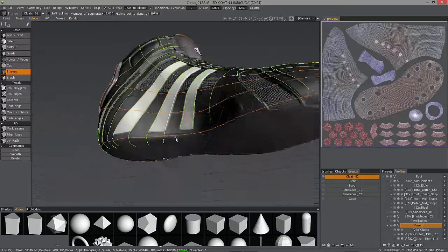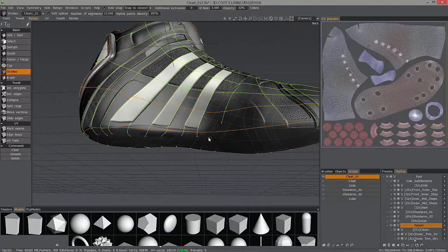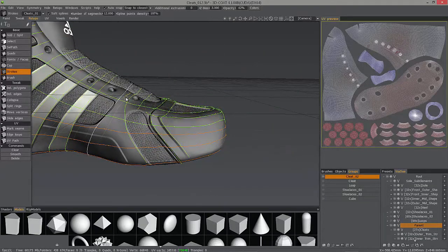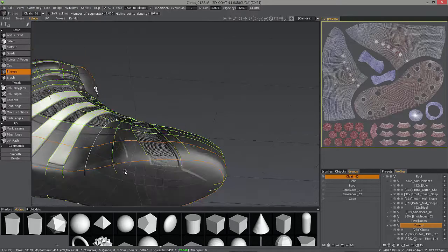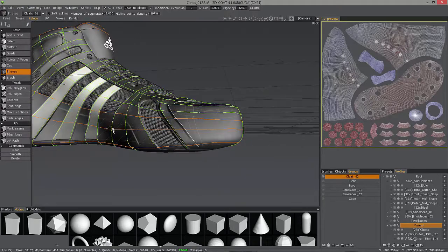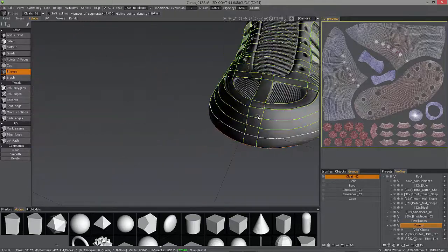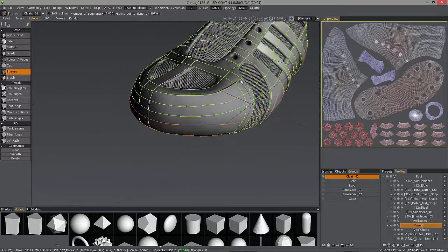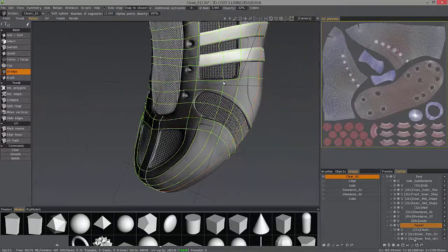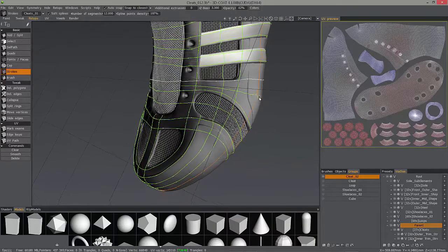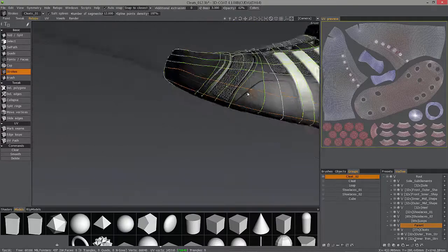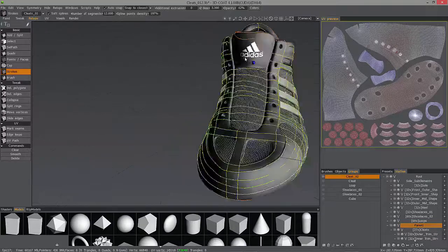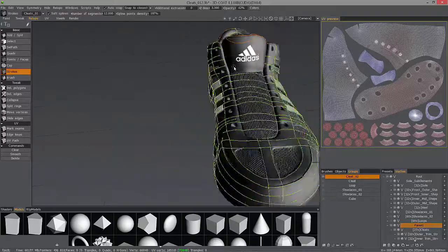And later on, what I do in this video is, if I've got overlapping objects like I do with the stripes, the heel panel, and some of the trim, sometimes I find that snapping will give you some difficulty. And I'm talking about the geometry snapping, not only with the strokes tool, but just geometry in general. So when you're working with all the polygons, sometimes 3D Coat will accidentally snap your geometry beneath an overlapping object.